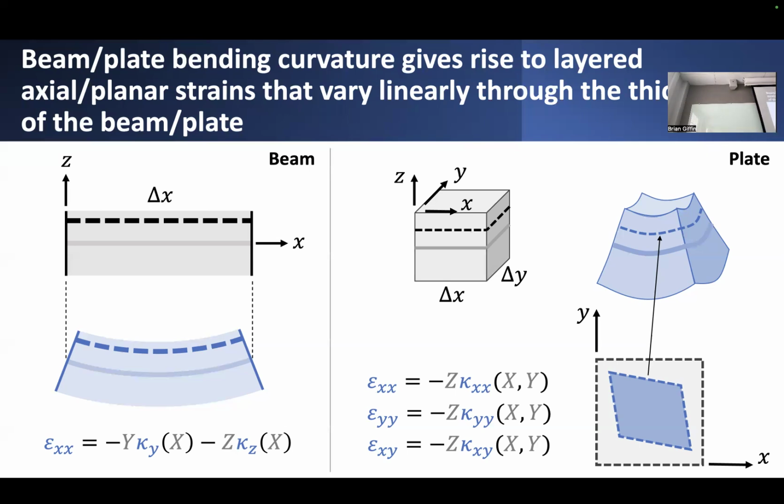But the idea here is that if I look above, let's say, the mid-surface of this plate, an analog to the conception of how neutral fibers in this beam maintained just the same length before and after deformation, the same applies to the mid-surface of the plate. It undergoes basically no in-plane deformations.